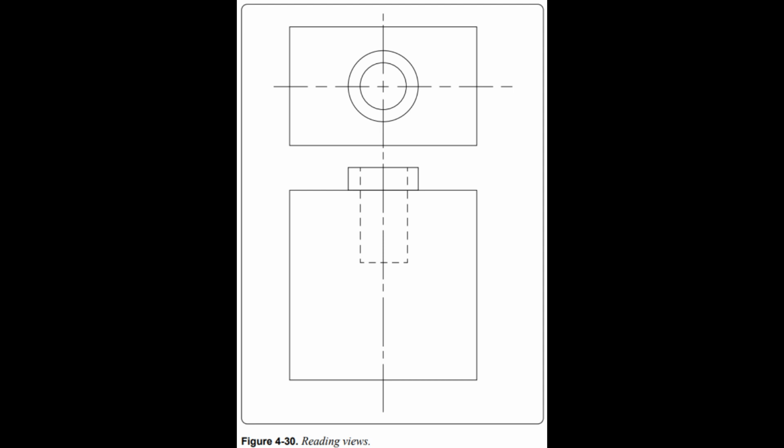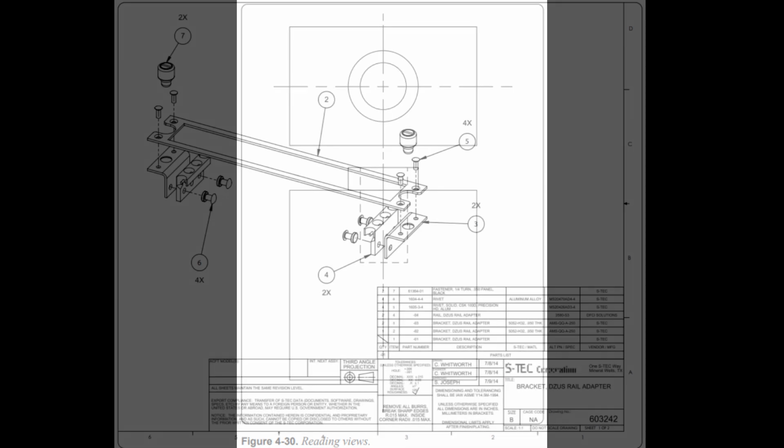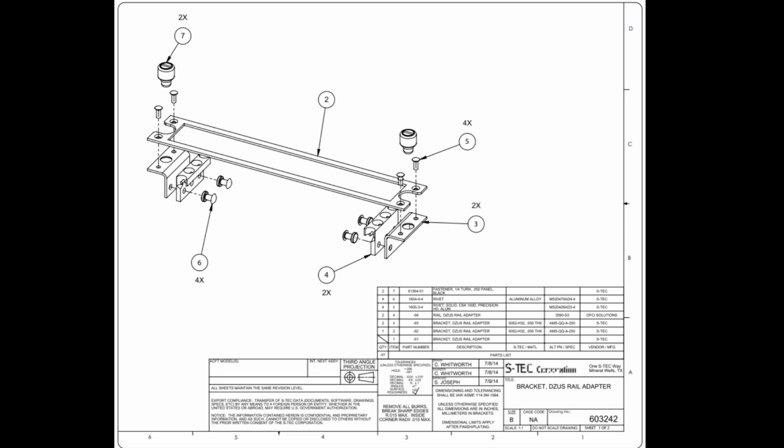End of page 4-20. Many drawings used for new aircraft and components are now using the metric system, and millimeter, mm, is the unit used for these drawings. Drawings may be dimensioned in decimals or fractions. This is especially true about tolerances. Instead of using plus and minus signs for tolerances, many figures give the complete dimension for both tolerances. For example, if a dimension is 2 inches with a plus or minus tolerance of 0.01, the drawing would show the total dimensions as